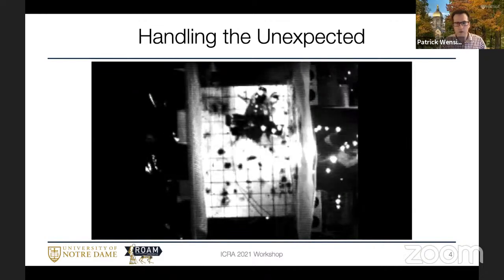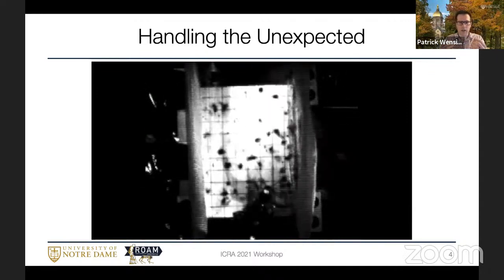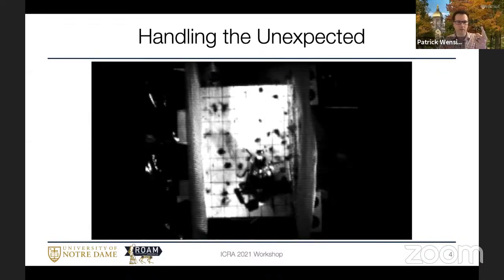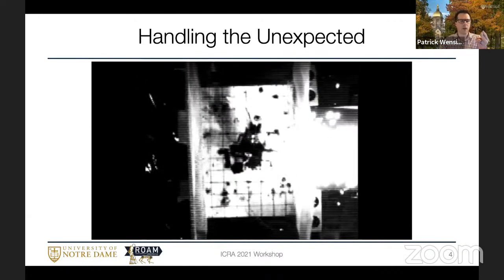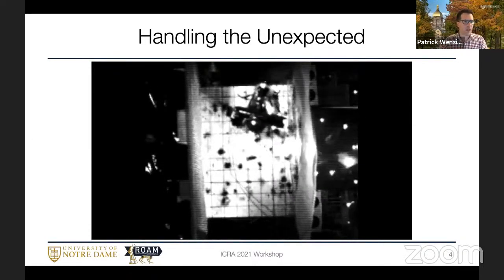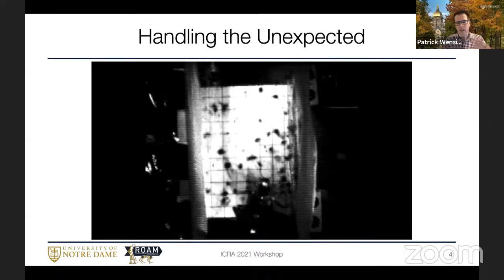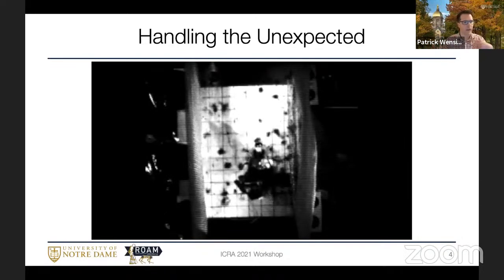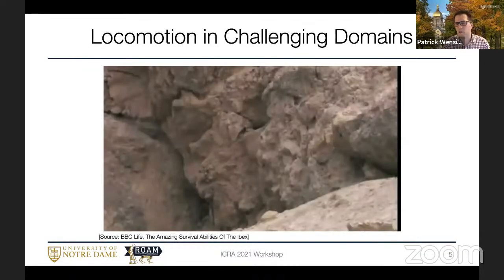And so the beautiful thing that they found when analyzing the ground force data following this disturbance was that the forces under the feet of the cockroach were, one, stabilizing to help recover its posture, and two, they occurred faster than could have possibly happened through closed loop neural feedback. That's to say that there's something with the body of the cockroach that had passive dynamics engineered correctly to help reject this disturbance. And so I think in terms of managing unexpected contacts, it's really a combination of brain and body. Here we see the body side, but of course, as we go into more challenging environments,